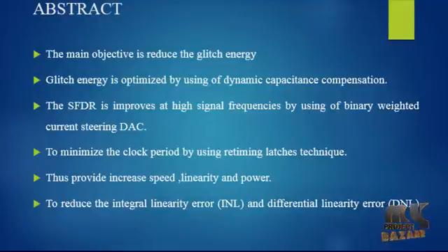SFDR is nothing but spurious free dynamic range. To minimize the clock period, the retiming latches technique is used, thus providing increased speed, linearity and power. To reduce the integral linearity error and differential linearity error, this project involves a glitch reduction approach by dynamic capacitance compensation of binary weighted current switches in a current steering digital to analog converter.